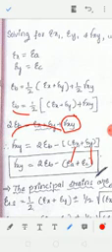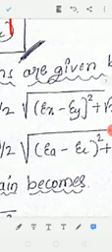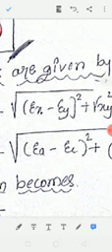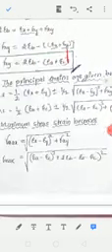If you know these three, then now we have to consider the principal strains. Already you know that epsilon 1 and 2 equal to 1 by 2 epsilon x plus epsilon y plus or minus 1 by 2 under root epsilon x minus epsilon y square plus gamma xy square.